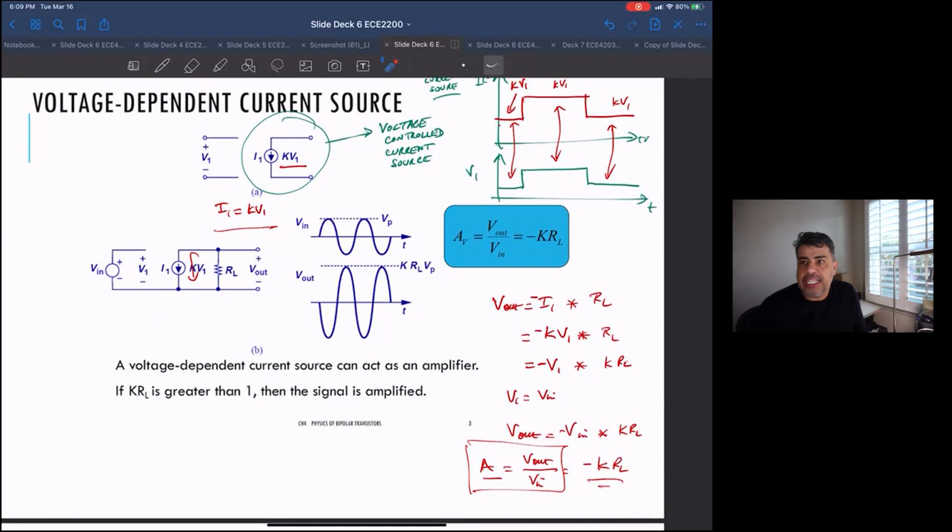But anyhow, the fact that you have a negative output amplifier actually really helps you, because you're going to use this negative version of the output, through a network of other circuit components, to bring it back to the input and linearize things and control things. It's slightly confusing, but don't let it confuse you. It's not attenuation. It's just a sign. So if V in is going high, V out is going low. But in either case, V out is a bigger version of V in in the voltage domain.